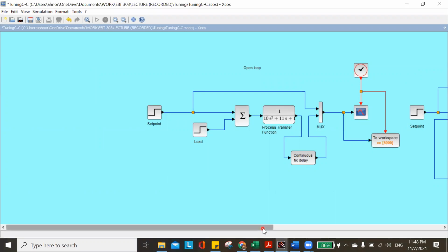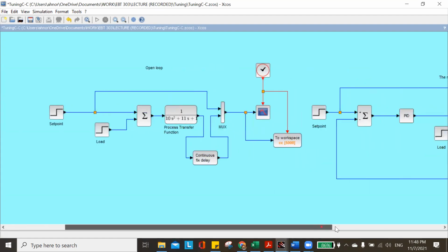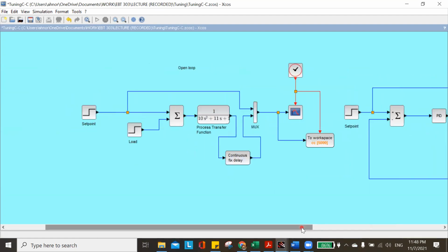Imagine that you have one complete automatic system and you want to know the starting point for the parameters of each controller. The first thing you have to do is switch off the controller of the system so that the system turns into a manual system.